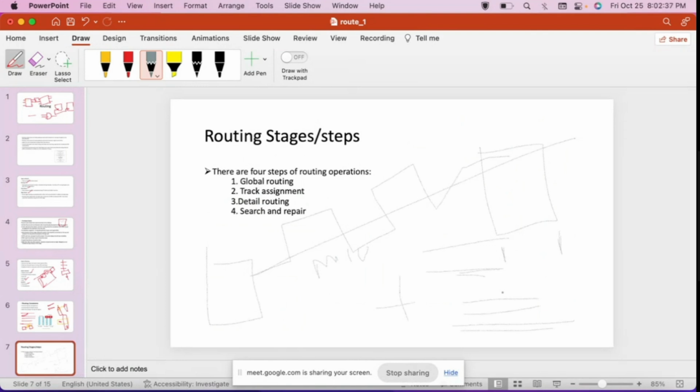During the construction, they indicate some tap points, and through those only it has to route. The same way, your design can be divided into some grid structure, and on this grid structure only you have to route. But for specific metal layers, when you move higher, it can go for a half grid.